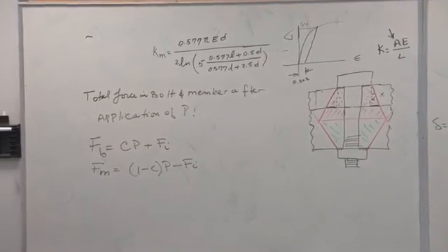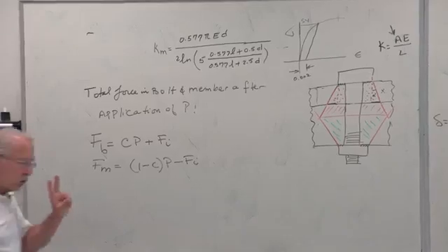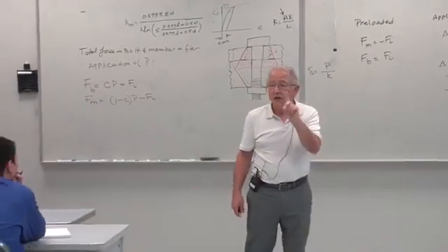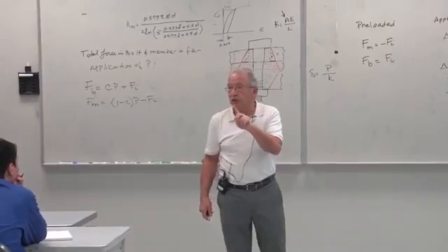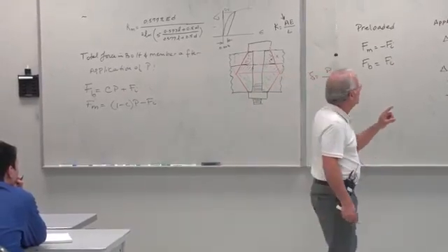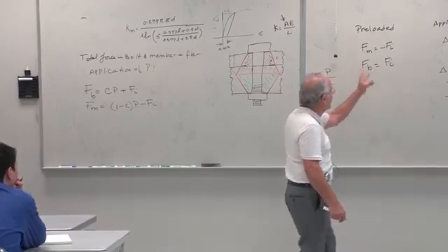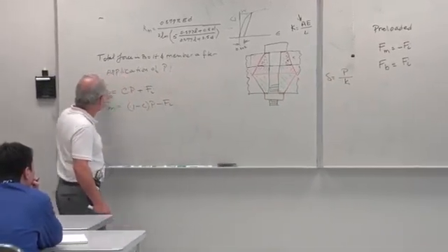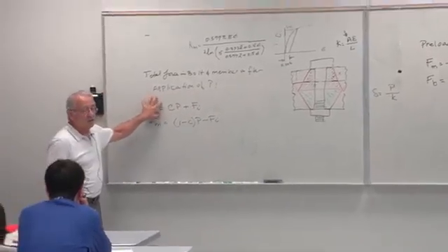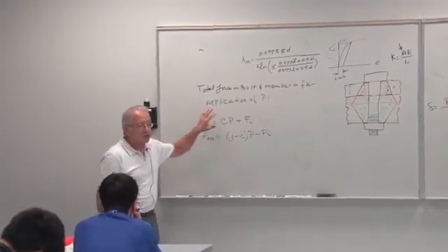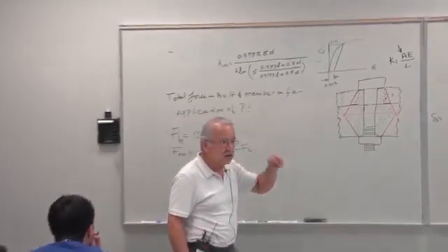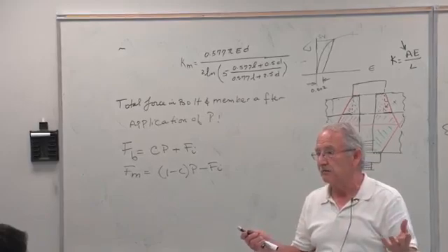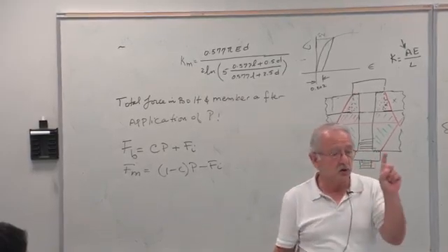Now we calculate all of this to make sure of two things. One, that the stress in the bolt does not exceed the proof strength of the material with some factor of safety. This is the force, but we have to calculate the stress. That's one consideration.